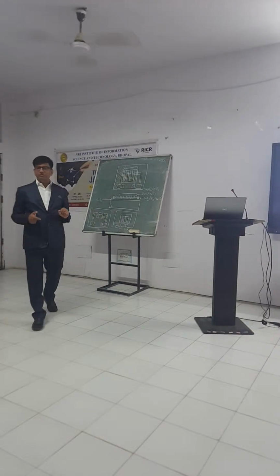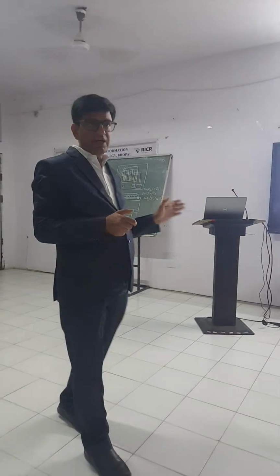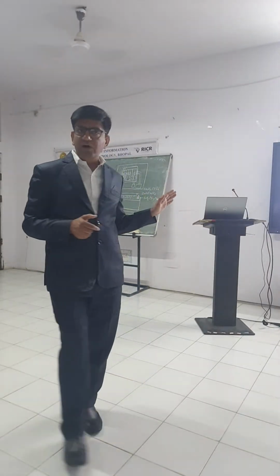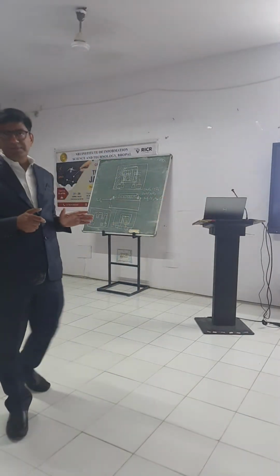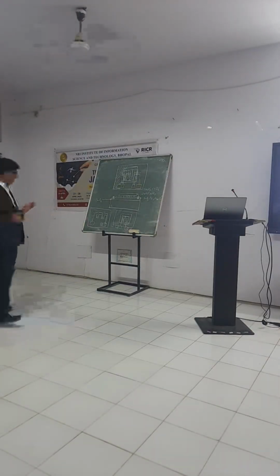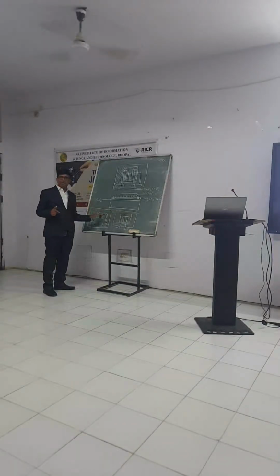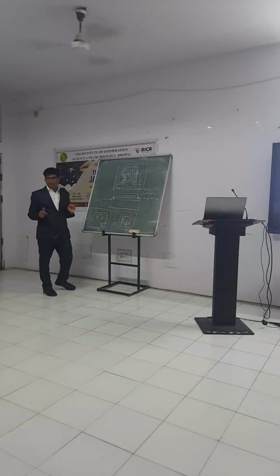How will I deposit the oxide layer? Now I can't go for thermal oxidation. So for that, what will I use? I will go for PECVD. Clear? With the help of PECVD, I will deposit an oxide layer or nitride layer over this complete wafer.